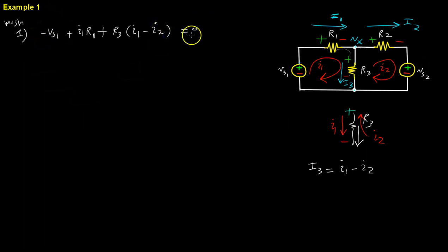This statement is a conservation of energy. It's telling me that in this loop there are voltage rises and voltage drops. So if I go up, I'm going to rise by some voltage. I'm going to go across the resistor and drop, go across the resistor and drop. And so that's what this statement tells us. Let's go ahead and find for mesh 2 what the voltages are.